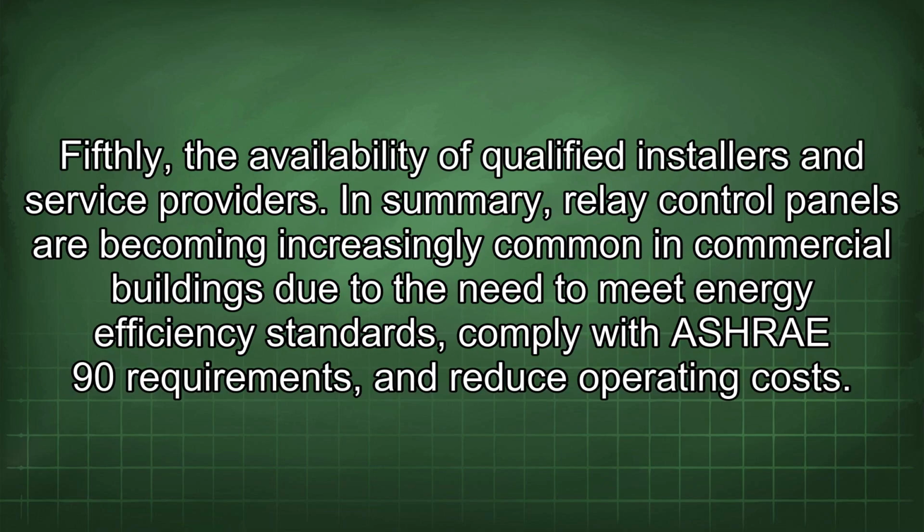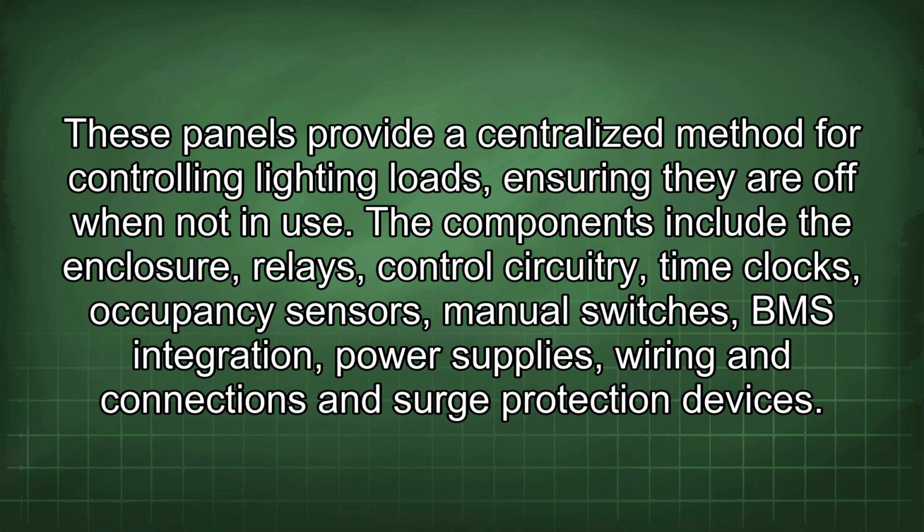Fifthly, the availability of qualified installers and service providers. In summary, relay control panels are becoming increasingly common in commercial buildings due to the need to meet energy efficiency standards, comply with ASHRAE 90 requirements, and reduce operating costs. These panels provide a centralized method for controlling lighting loads, ensuring they are off when not in use.